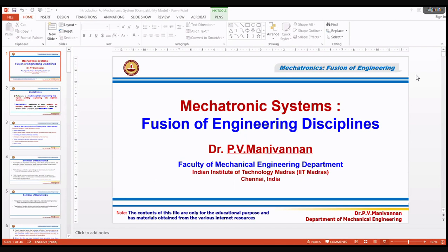Then you have headlamp, tail lamp, and if the car has a multi-cylinder engine, a fuel pump may be there to suck the fuel from the tank and supply it to the carburetor. At that time fuel injection was not there, correct? A diesel engine had an injector, but a petrol engine only had a carburetor. So these are electrical things. No electronics, no computer, no sensor, no ECU, no program, nothing.